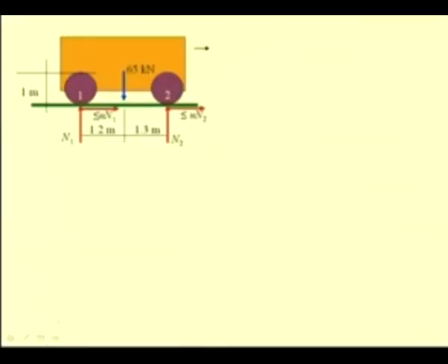So, this shows the various forces that are acting. Let us say N1 be the total of the reactions because of the 2 wheels in the rear, and N2 be the sum total of the 2 wheels that are situated in the front, and the frictional force that can exist at maximum is mu times N1.